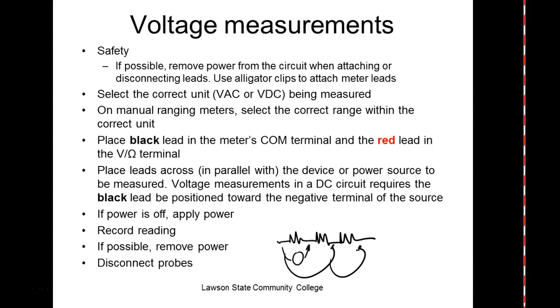So if you can, turn the meter off. Turn the power off to connect your meter. Especially if you get up, what's the lethal voltage? What do they consider lethal voltage? 50 volts. Anything above 50 volts is considered to be lethal. It doesn't mean something below 50 volts can't be lethal, but anything above 50 volts is considered to be lethal.